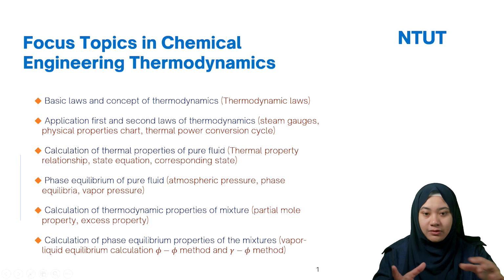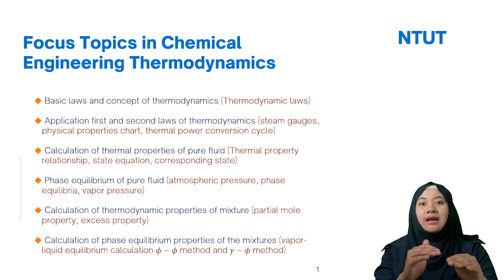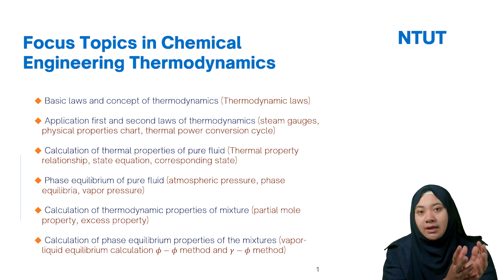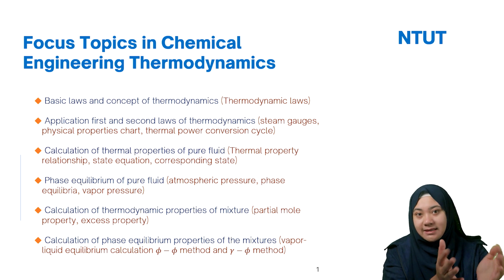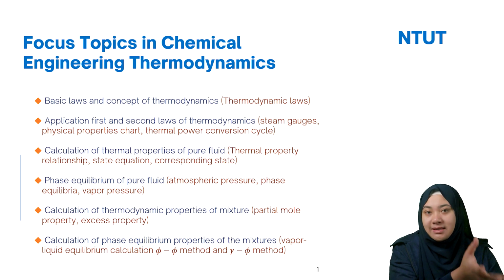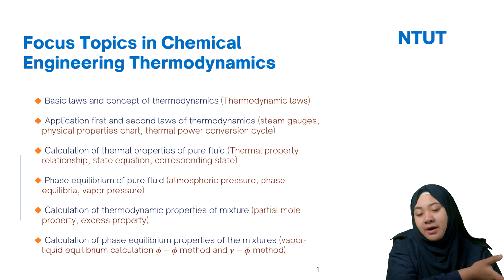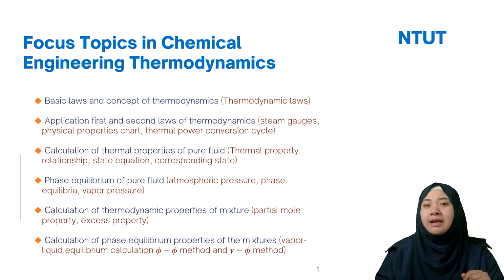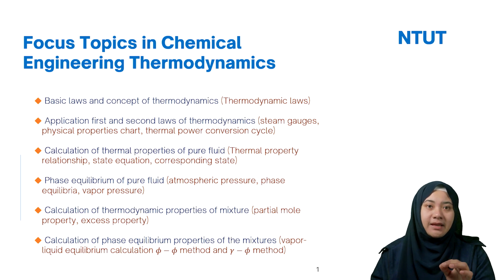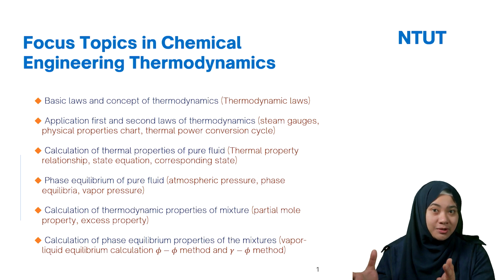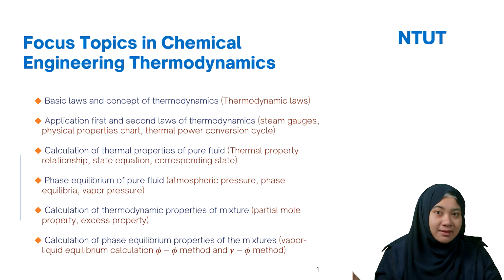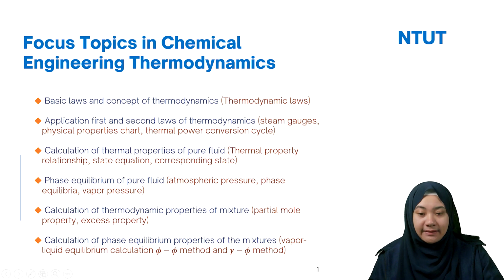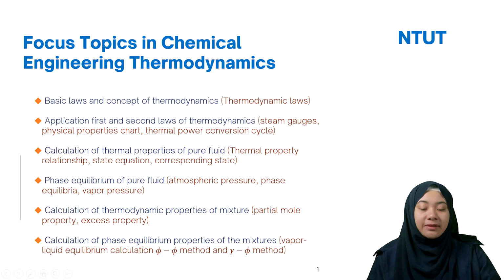If you have a single or pure fluid, it means one component only, and then you have the binary system, with two compounds, and the ternary system, three compounds, or quaternary, four components. So the phase equilibria is not similar, because each has different properties. Even for pure CO2, when you mix CO2 with amine, they are totally different. So in thermodynamics, you need to know properties like phase equilibria at atmospheric pressure or even high pressures.